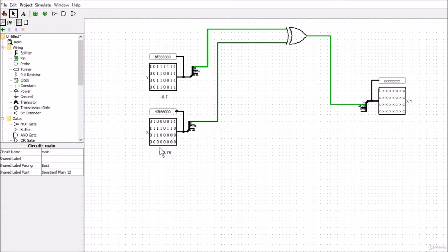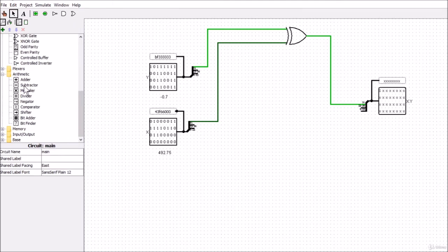So let's go ahead now and we'll do our first part of our exponent. So the first thing we wanted to do was subtract off the value of 127. So we can head down into a subtractor here. So we'll put one subtractor, and I'll just leave it at this point here. So here's a subtractor. Now at some point, there's not a lot of room in the screen here, so I will have to move sections around a bit as we go along.